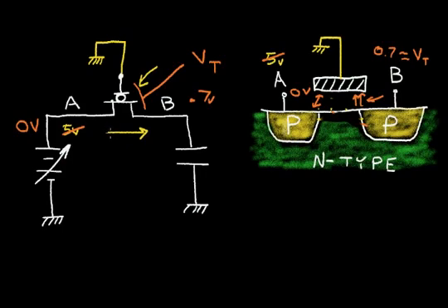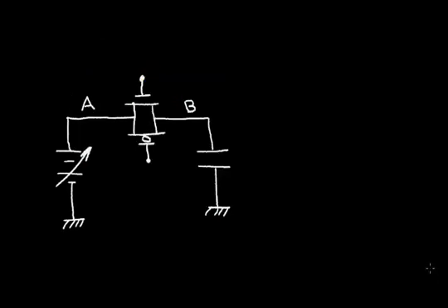So what's the solution? Well, let's look at the solution. The solution is to put an NMOS transistor in parallel with a PMOS transistor. When we want the switch to be closed, we'll put the NMOS gate at 5 volts and the PMOS gate at 0 volts. And regardless of what the voltage is at the battery, if we have 0 volts at the battery, the N channel will do most of the work